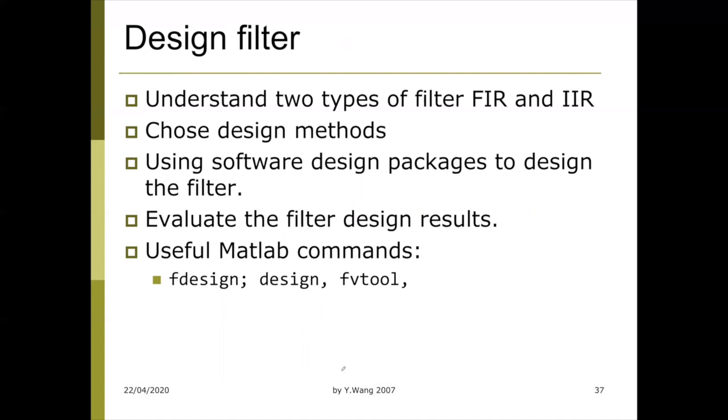It's in MATLAB again. I gave you loads of theory. It's probably confusing. It's quite a complex area, but it's a starting point, so you understand the basic idea, at least intuitively. I hope you understand how filter design works. But in the modern engineering era, we have very good engineering software to help us. In MATLAB, there are basically three commands to help you: fdesign, design, fvtool. I think we touched a bit on them in the practical already. Those basically implement the algorithms I talked about in the slides, maybe with advanced alterations.